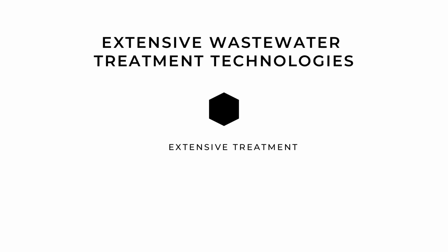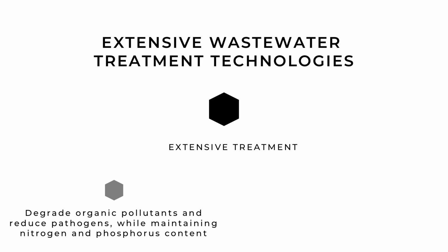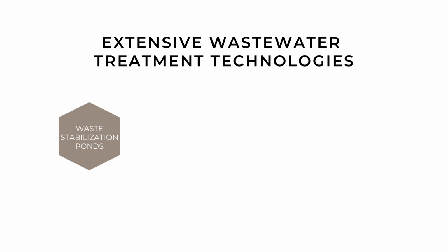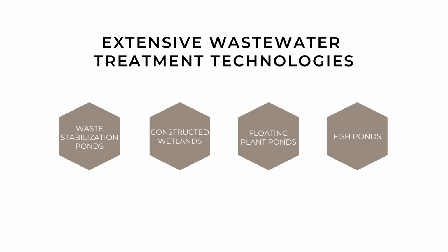I will focus on extensive wastewater treatment technologies that are robust and well established in developing contexts. They are also able to degrade organic pollutants and reduce pathogens while maintaining nitrogen and phosphorus content, which is key for water reuse in irrigation, forestry, and aquaculture. Another benefit of extensive technologies is the possibility of combining primary treatment, secondary treatment, and post-treatment in one unit. These technologies are waste stabilization ponds, constructed wetlands, floating plants, and fish ponds.